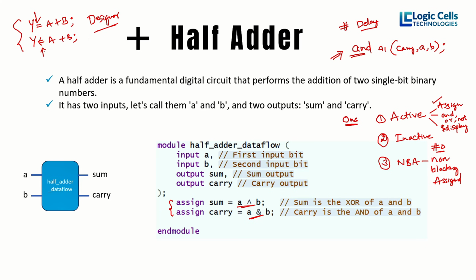All non-blocking statements that you write will execute in parallel, but blocking assignments, if you write one after the other, will execute sequentially. All these things are very important in Verilog. Those will execute in the third stage, within 0 nanoseconds itself. For you it is 0 nanoseconds, but for your simulator, 0 nanoseconds is subdivided like this. It executes active statements first, then inactive statements, then it will update the NBA statements, then it will update the monitor statements.